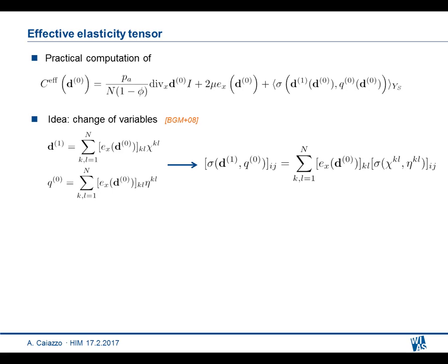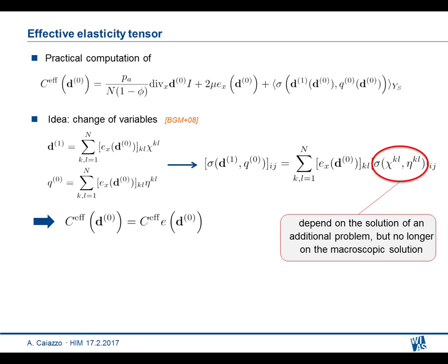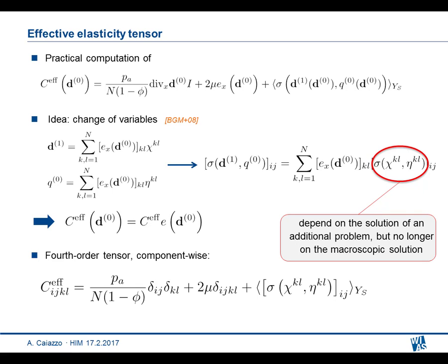If you do this, then everything is linear, so you can write this sigma, just taking out the rotation. Okay. And then you can plug this in the equation above. So you can see that you can actually write this tensor. You can separate the deformation tensor from the C F, so you get an expression of a 4th-order tensor where this term now doesn't depend on the fine scale. So it's an equation which you can solve independently given the setting.